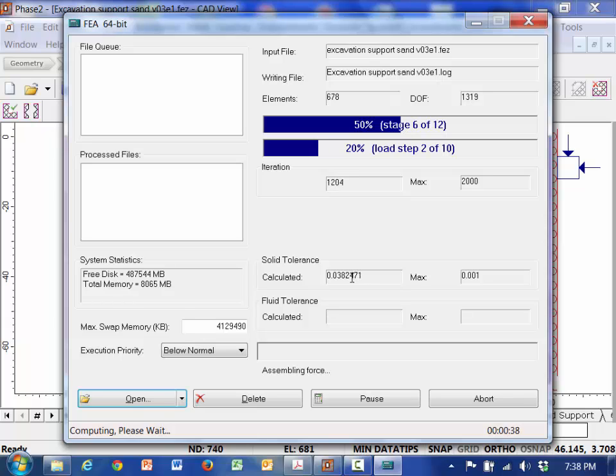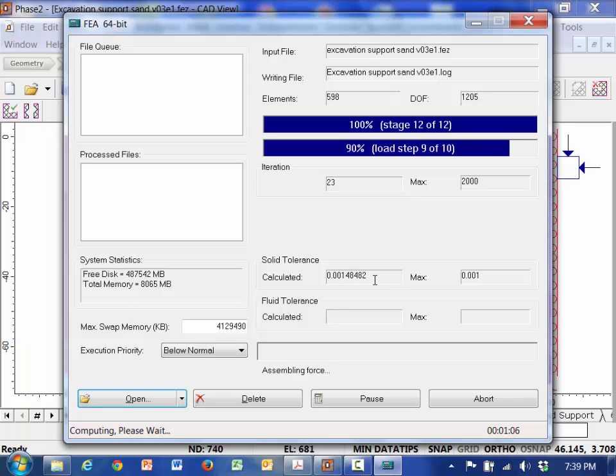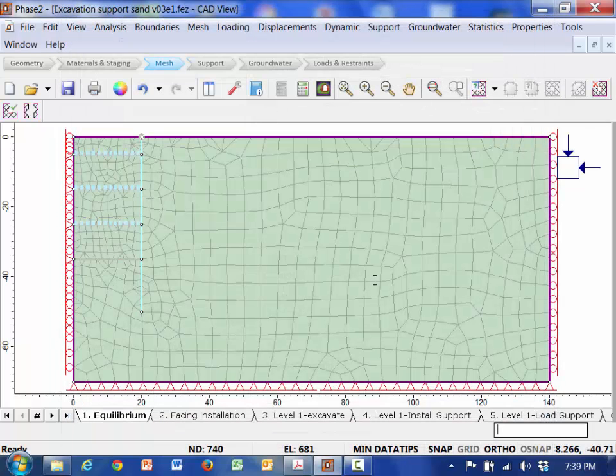If it's not converging, it usually means you don't have a very good mesh. There's something wrong with your meshing. So I think we've already got one step that didn't converge. So that one didn't converge either. I'll show you how you know whether they converged or not. So don't just go happily along turning in results when the algorithm didn't converge. When it didn't converge, it means you don't know what's going on.